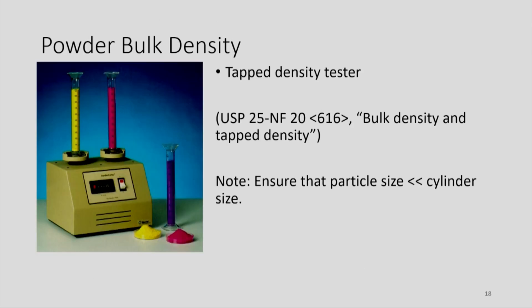So common is one sample instrument, but for grains and large materials, there are large cylinders that allow us to tap a big volume of powder. You load the samples in cylinders, fix the number of taps you want, and then get the change in volume and get the tap density. Okay.